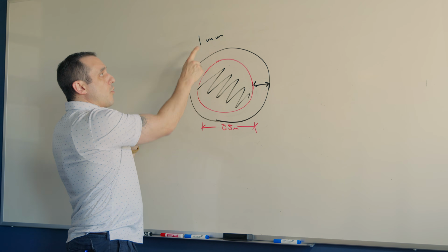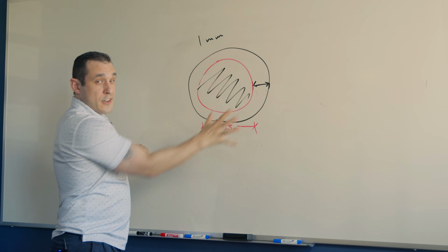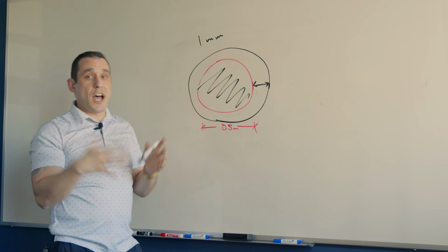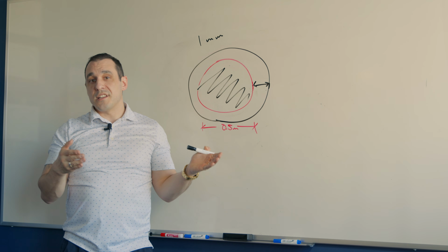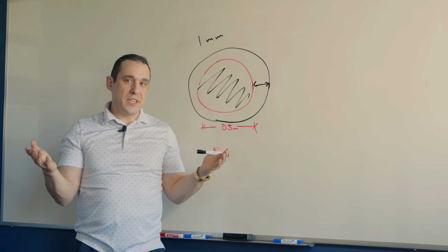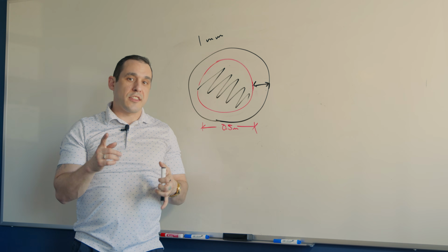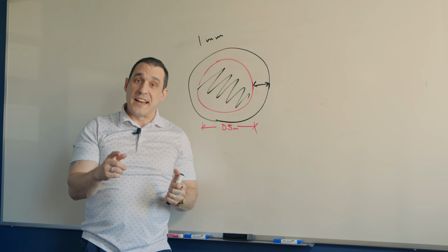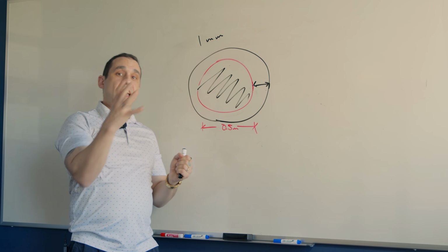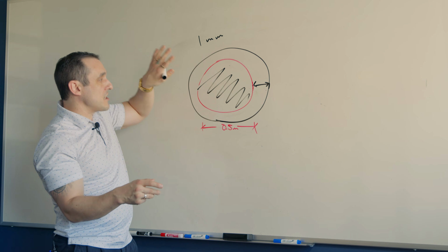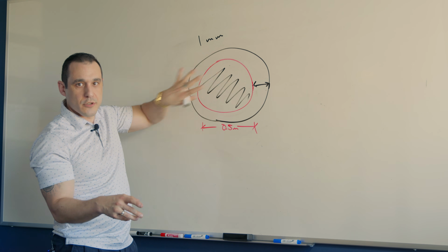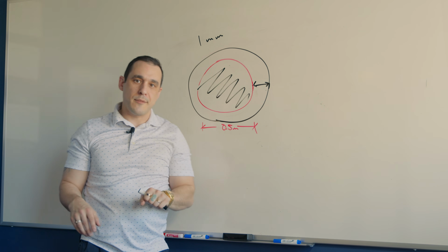Now typically with a 1 millimeter pitch BGA, we aren't actually doing any of this because we're not doing via in pad. The reason is that if you look at a typical PCB layout that has a 1 millimeter pitch BGA, you will see that the fan out is actually dog bone fan out. And that's where the vias are offset from the pads and they aren't actually sitting in the area where solder is going to hit onto these landing pads.